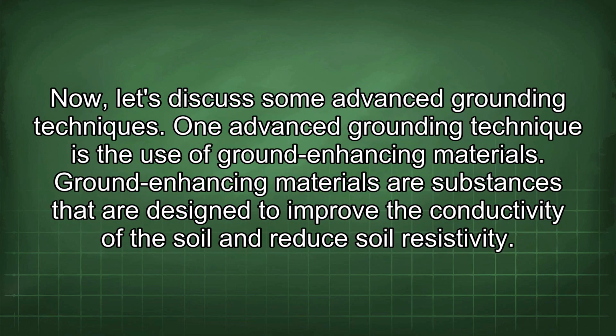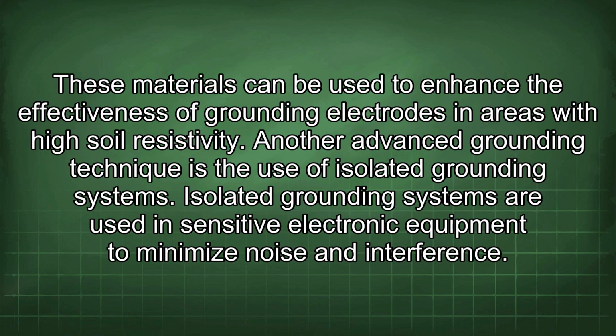Now let's discuss some advanced grounding techniques. One advanced grounding technique is the use of ground-enhancing materials. Ground-enhancing materials are substances that are designed to improve the conductivity of the soil and reduce soil resistivity. These materials can be used to enhance the effectiveness of grounding electrodes in areas with high soil resistivity.